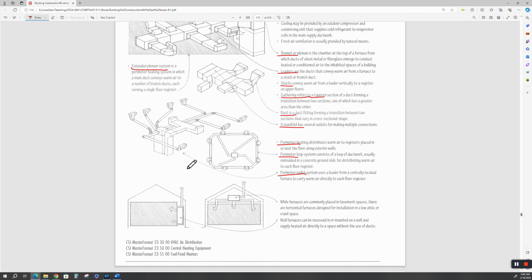Well, they had hell doing the air balance in the welding lab at Cypress Center. Because you've got these giant exhaust fans sucking out the welding gases while you've got the rooftop units dumping in. So the welding exhaust system, the Niedermans, pulled out more air than the RTUs could put in. So the RTUs were basically dumping the supply air into a vacuum. And they were really running up on their fan curves, and they would overdrive the motors and break their mounts, and it took them a while to figure that out.